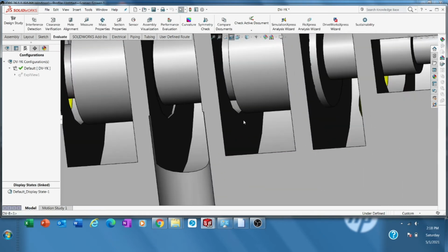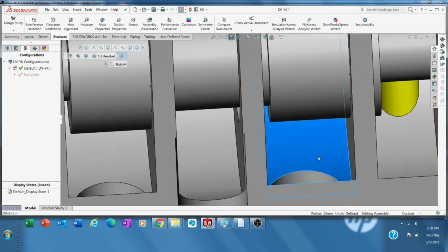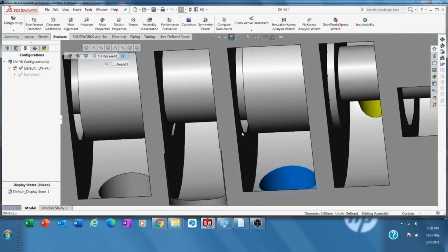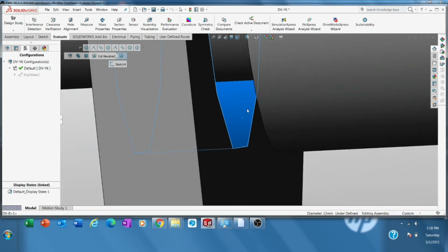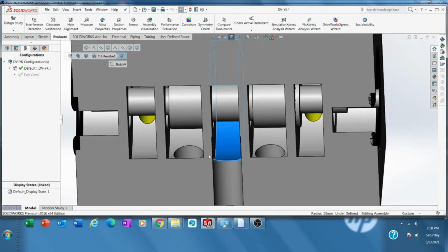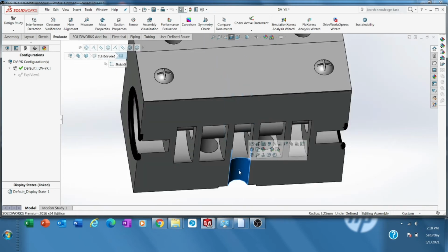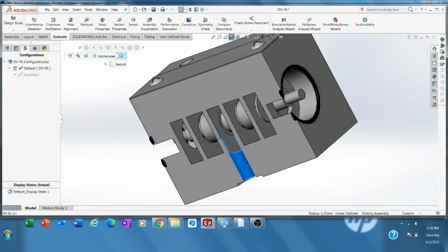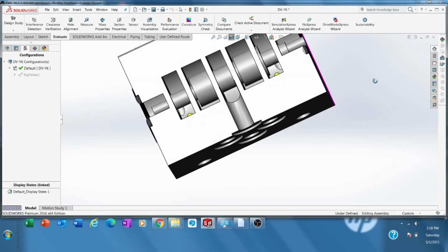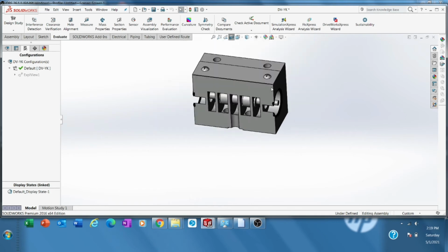So this is more clear. The liquid returning from the A port, there is a gap here, an opening, there is no opening here, it's closed, so it moves here, and then it goes to this hole, and this hole is the tank port, T port. So now I think it's very clear.